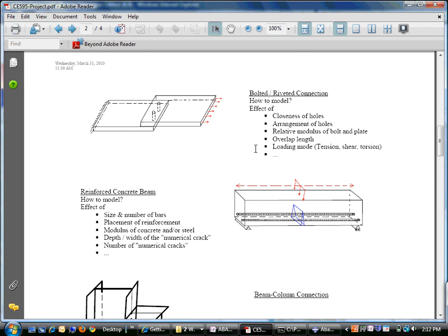Another problem that you could take a look at is this reinforced concrete beam. If you choose a linear elastic material for this concrete beam, and let's say there is no crack in the middle to begin with, and if you choose then to model this concrete beam with a rectangular cross section, then you can create two separate cylindrical rods for the steel part.